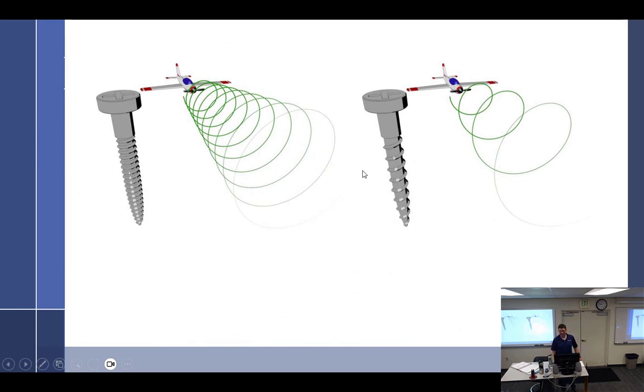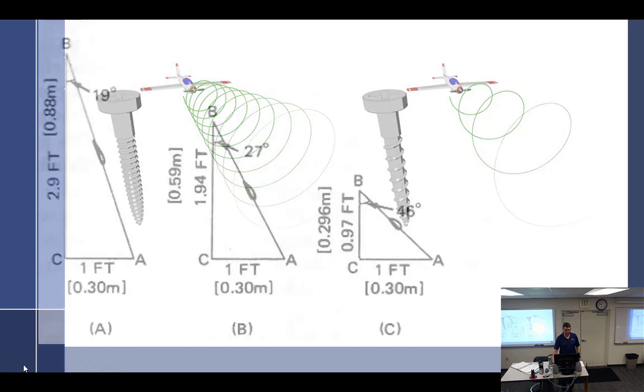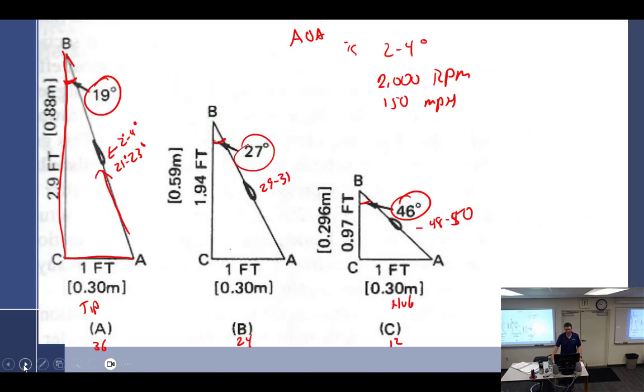If you go back to the page right before, this one? Yeah, that one. So the angle of the hypotenuse to the vertical axis up here would be where the wind is hitting the prop. So that's where the wind is hitting the plane of rotation of the prop. That's the angle of the wind at that spot, relative to the plane of rotation. Yes. Okay. No, not relative. It is the angle of it. That is where the wind's coming from. It's coming from 46 degrees.